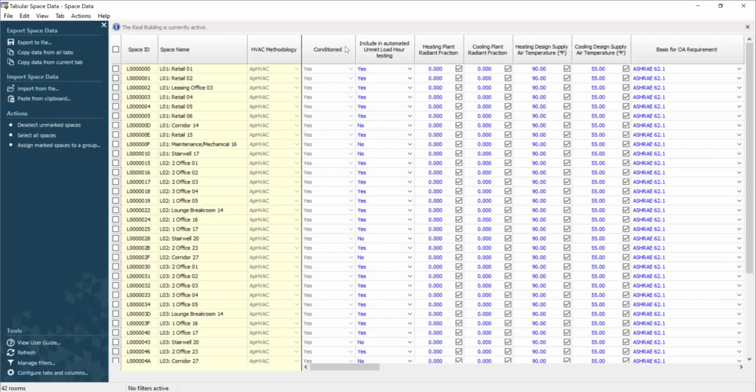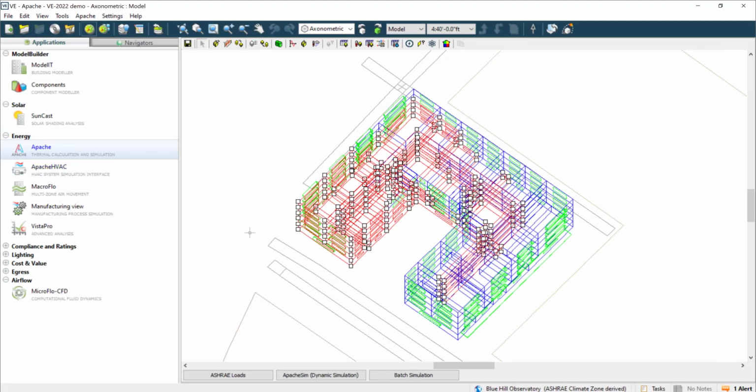We even give you options to either export the entire thing or export stuff from a certain tab, and then paste it into Model B, or you can use the Master Template Wizard. And then finally for HVAC systems, that's just a file, so you can move that file in Windows Explorer. You don't even have to do that natively in IESVE. The only thing you need to do potentially is reassign your zones.